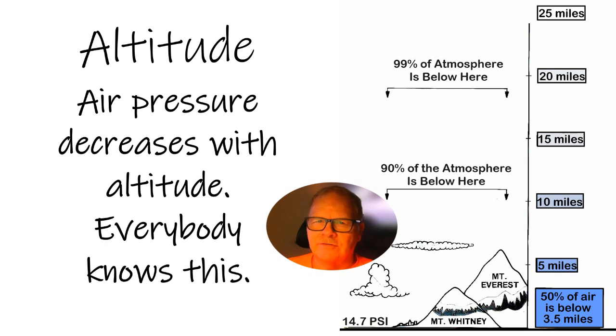If you've ever driven a carbureted vehicle in the mountains, like if you go on a vacation trip and you start out at a place that's near sea level and you head up into higher altitudes, you'll be ashamed of the way your vehicle runs, because it runs terrible. So that's why for altitude modification you have to advance the timing and some other stuff. But the long and the short of it is, here you are with the decrease in pressure at altitude.